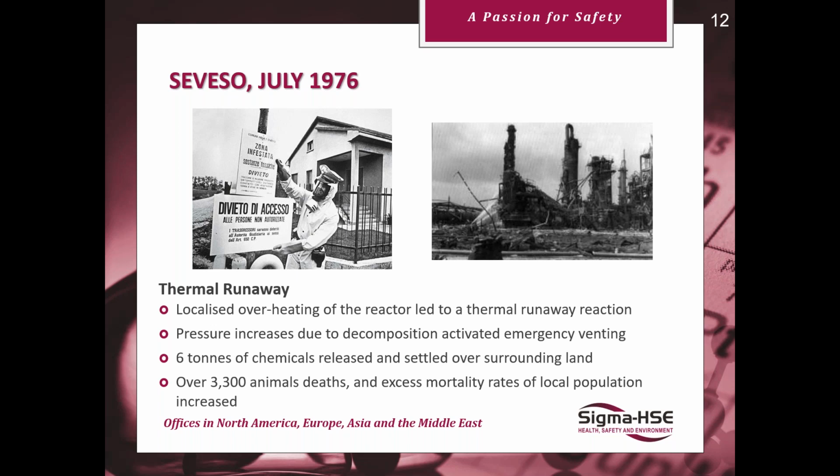We'll go through later some of the common causes of runaway events. So we had the out of process occurrences here of the higher temperature, stirring was ceased, and there were also not the catches in place, such as there was no temperature reading available on the steam lines for the operators to see and react to.